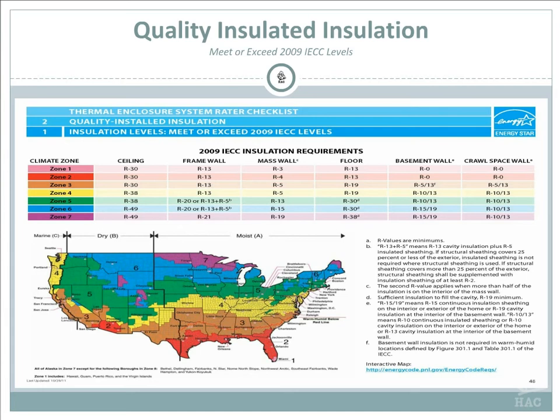We handled those a little bit differently back in those days. Basically, you used to lay a 6 mil visqueen on the ground for your vapor barrier, and then you insulated the perimeter with fiberglass insulation. I like that theory instead of doing floor. We'll talk about floors in a little bit.